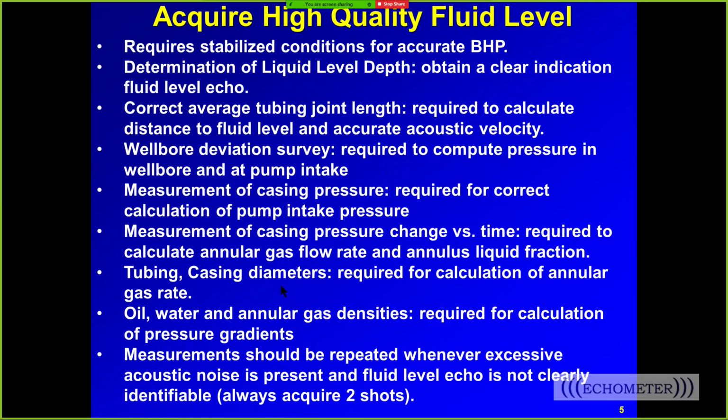Other than that, if you don't have data, my recommendation is shoot the well, even if you don't have all the data. Later, when you go back to your office, you can update additional data to the shot and then reanalyze it. But don't walk away from the well because you don't have the water gravity or the oil gravity. Go ahead and shoot it, and you can update that later on. So shoot it.